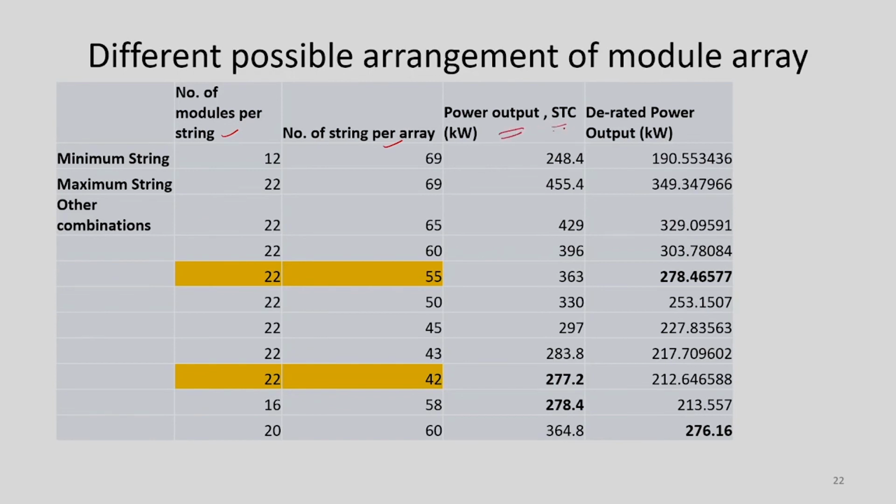One is at standard test condition and the other at the rated power output. When rating factors like manufacturing tolerances, temperature and dirt are considered, the rated power output is about 230.137 watt, and for standard test condition it is 300 watt peak.